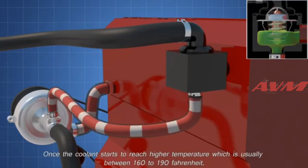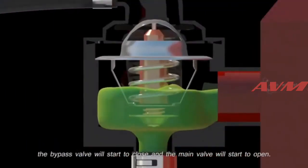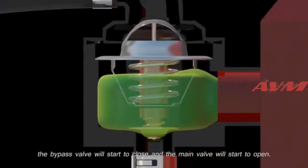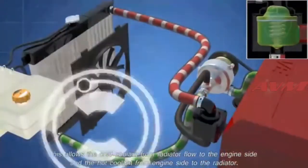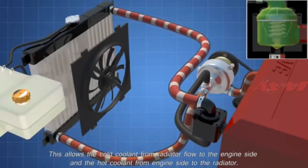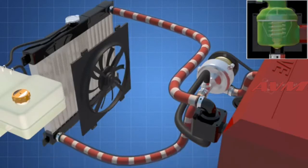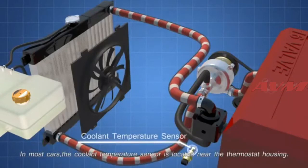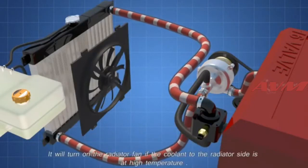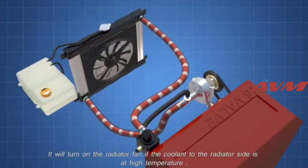Once the coolant reaches a higher temperature, which is usually between 160 to 190 Fahrenheit, the bypass valve will start to close, and the main valve will start to open. This allows the cold coolant from the radiator to flow to the engine side, and the hot coolant from the engine side to flow to the radiator. In most cars, the coolant temperature sensor is located near the thermostat housing. It will turn on the radiator fan if the coolant to the radiator side is at high temperature.